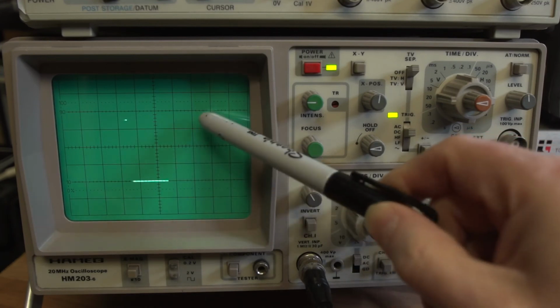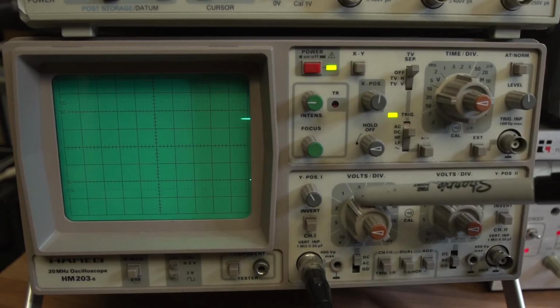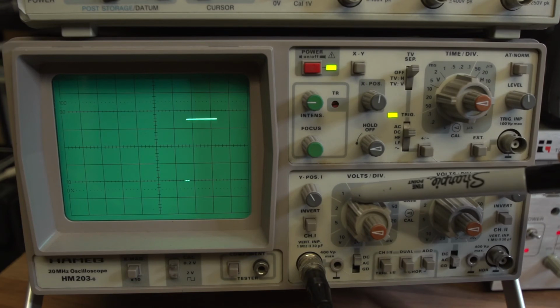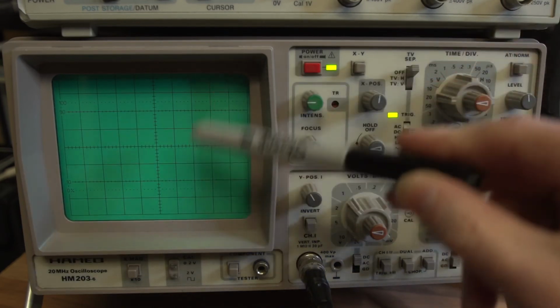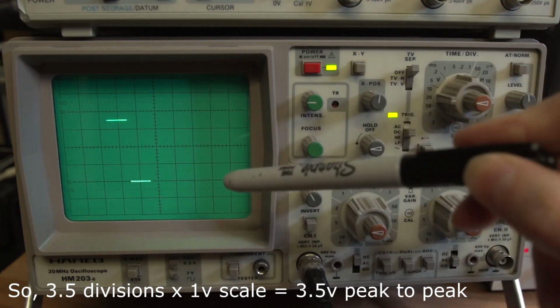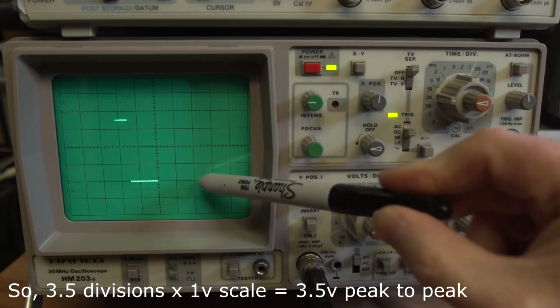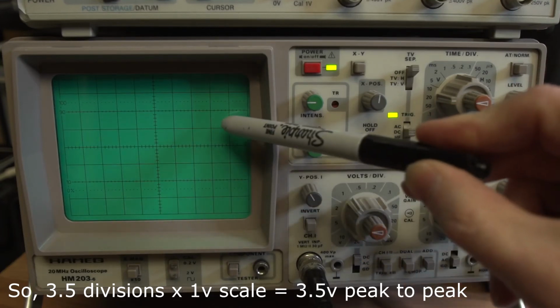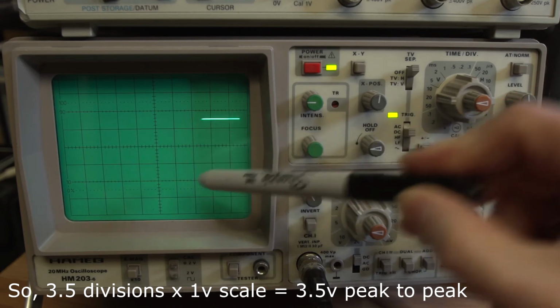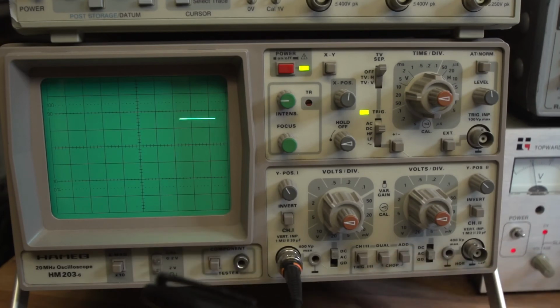So it's 3.5 multiplied by the attenuator for voltage input. And at the moment it's 1 volt per division, so it's very simple. 1 times 3.5. The amplitude is 3.5 volts. So straight away that's telling us the voltage of the waveform, peak to peak, from the most negative part to the most positive part. So that's 3.5 volts. Now what about the frequency or the time period?